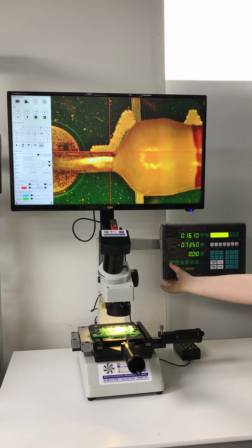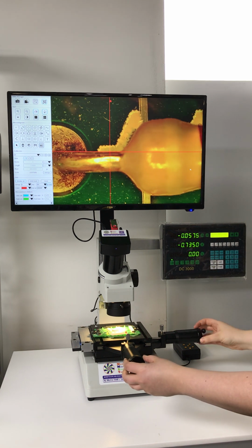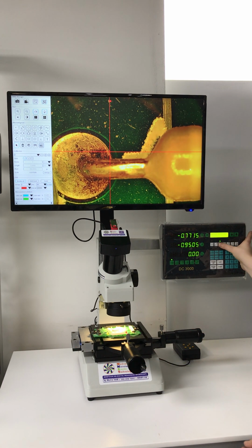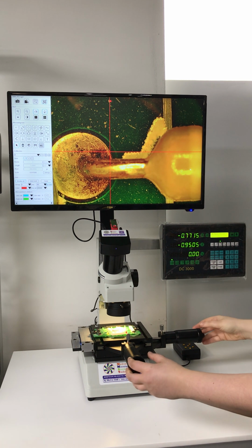You can also do programming. So if you measure certain parts all the time, you can do a program. So do record program, press enter, give a program number, we'll do 1, press enter, and let's do a position. Let's say we always measure a circle like this. So press circle, and I always want to do, let's say 6 points. So I'll press the circle again.